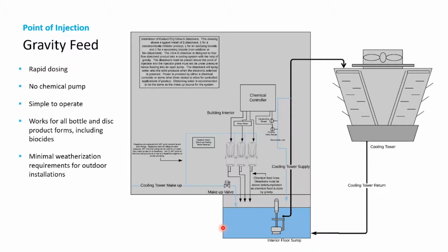Typically, these dissolvers are actually cheaper than a lot of the chemical pumps. Very little to no maintenance, and they work very well in applications where you want to mount a chemical system on the side of a cooling tower. There's people that mount these on the side of the towers, punch a little hole through the exterior and drop a line into the sump of the basin of the cooling tower, and they provide treatment that way.